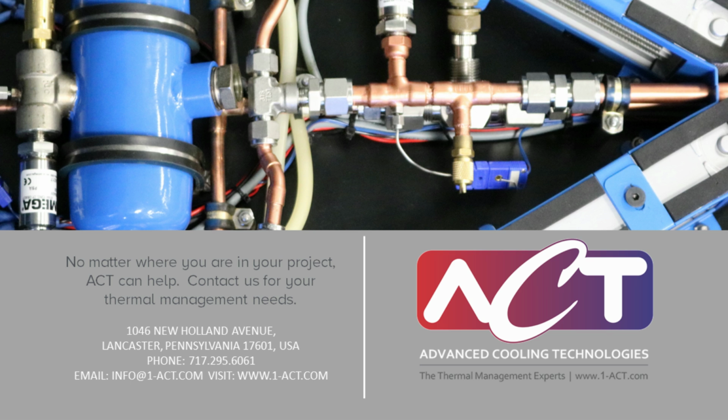Being a newer technology, it tends to fall under a lot-based type qualification, and you have water as a working fluid, and it goes up to space where your systems tend to run cold whenever you're in eclipse. Water obviously expands as it freezes, so one of the main concerns or tests that we see are environmental-based, putting some proof of concept thermal freeze-thaw cycles on the systems, powered freeze-thaw, what happens whenever power is being applied as the system goes to a frozen condition, and all that working fluid wants to depart from the evaporator and condense and freeze in the condenser.